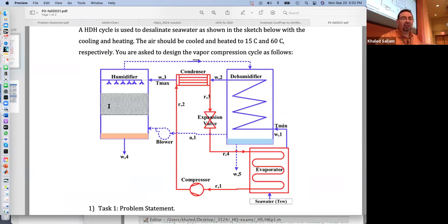So that's why they let it drip into a bunch of trickling trays, so that a water film forms and drops, and meanwhile the air has to navigate all those passages. As a result, when the air leaves here, ideally speaking, it can be 100% humid because you sent it through tons and tons of water passages. It had a very big chance to hang with water for a really long time.